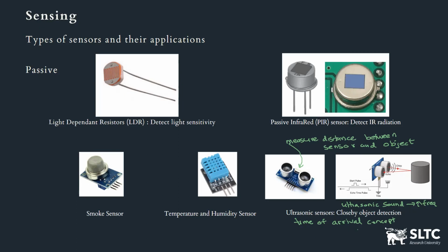So the sensor will estimate the time it took for that wave to go to the object and come back to the initial location, and using the time of reception minus the time of transmission, that we will calculate, and based on that difference, the distance between these 2 points will be calculated, right? So we know already the velocity of the wave that is transmitting.